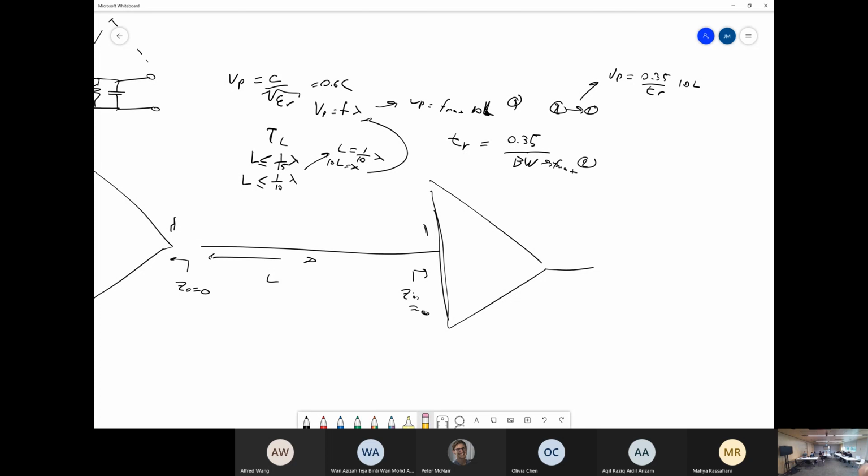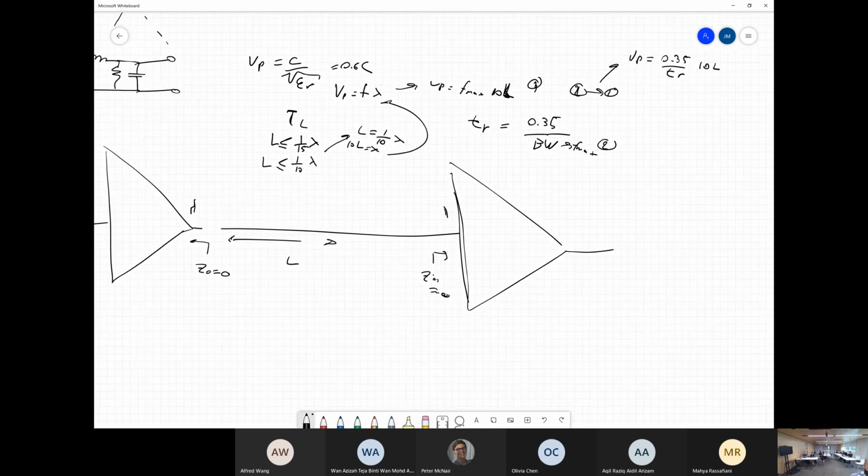Now, let's say you do want to worry about impedance matching. Again, this is an insane oversimplification. If anyone saw me do this, I'd get decapitated. If you have a high impedance, your wave will reflect back perfectly, with a phase of 1 and an amplitude of 1. If you had a short circuit, it would reflect back perfectly, but with a flipped phase. So if I launch a wave here, it reflects back with the same phase, and it hits here, which is like a short circuit. It reflects back with a -1 phase, then +1, then -1, then +1, then -1. It's going to keep bouncing back and forward forever.